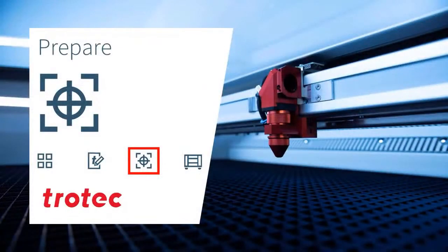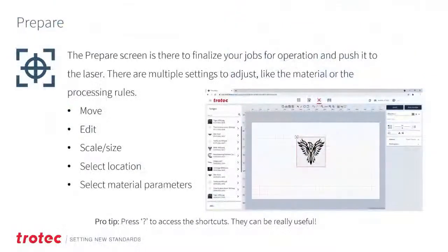Next, we're going to go through the third screen called the prepare screen. The layout of the prepare screen is very similar to the job control software with many added benefits. The prepare screen is there to finalize your jobs for operation and then push it to the laser. Multiple settings can be adjusted in this screen, such as the material or processing rules. The prepare screen also has additional editing capabilities such as scaling or sizing, determining where the file will be processed on the laser field, as well as selecting material parameters.